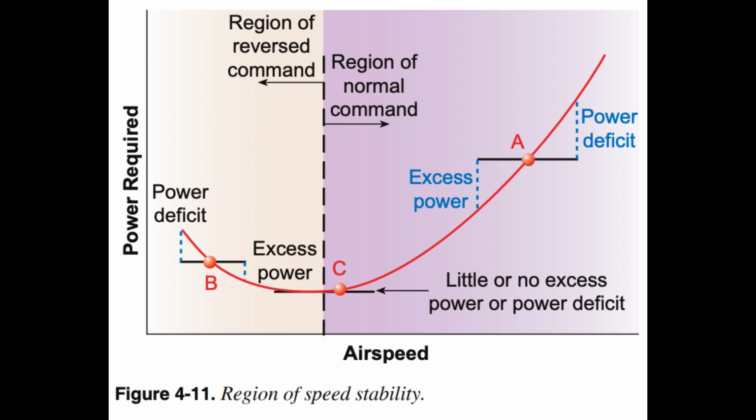Work is the product of a force moving through a distance and is usually independent of time. Power implies work rate or units of work per unit of time, and as such is a function of the speed at which the force is developed. Thrust, also a function of work, means the force which imparts a change in the velocity of a mass. During takeoff, the aircraft does not stall even though it may be in a climb near the stall speed. The reason is that excess power, used to produce thrust, is used during this flight regime. Therefore, it is important, if an engine fails after takeoff, to compensate for the loss of thrust with pitch and airspeed.